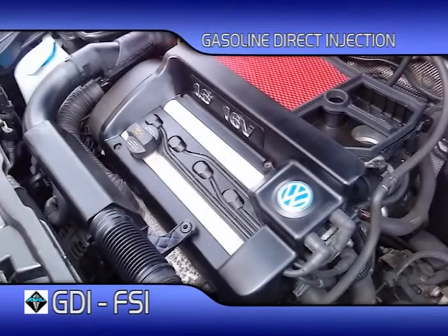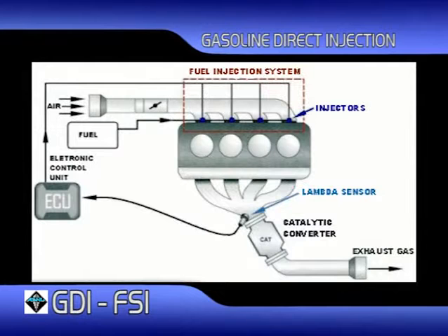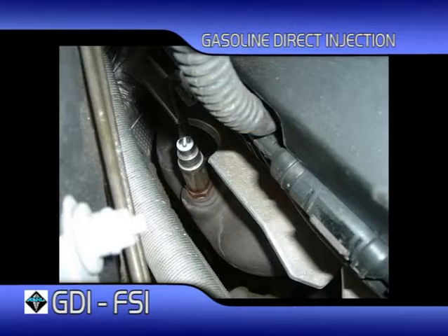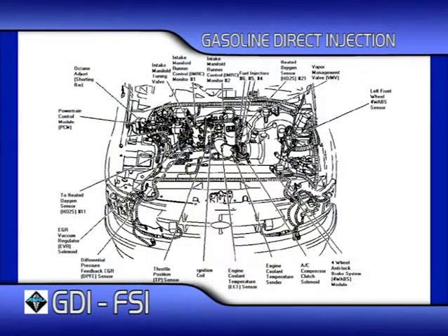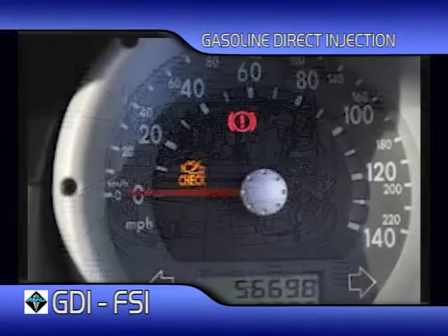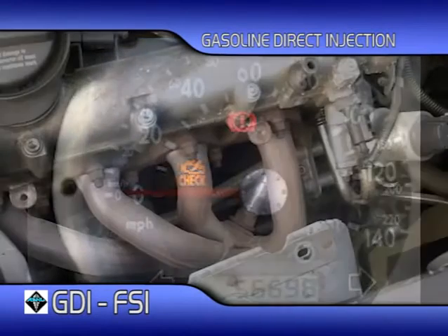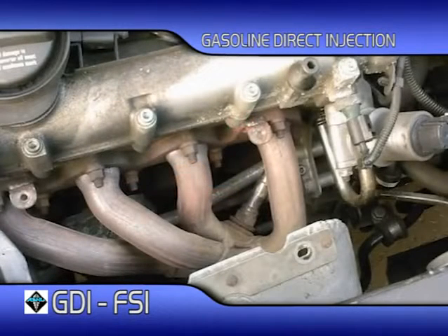The engine management system is designed so that, should an injector fail, the pressure would immediately force the valve shut and no fuel would exit the injector. Immediately, the engine management system would identify that no fuel was in the combustion chamber through various sensors on the engine and immediately stop the cylinder spark plug from firing. It would then illuminate the engine check light and in some systems switch the engine to limp mode until the problem is eliminated. The same would happen if there was a serious intermittent problem.